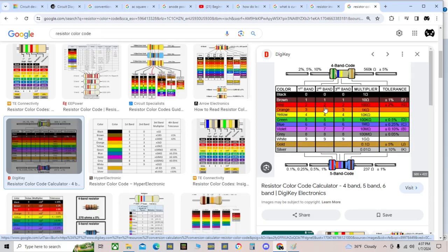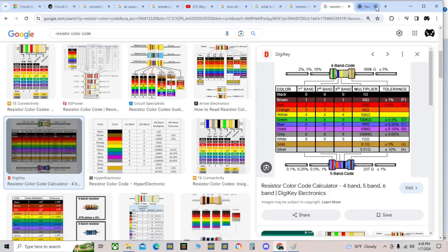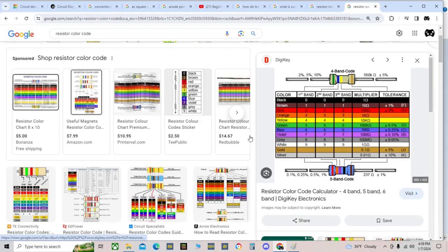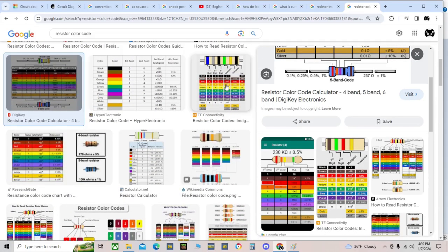Then we've got to find blue. 5, 6. Oh, multiplier 10. Oh, okay, I didn't see that. I'm blind. But yeah, just the multiplier, and then if they have more, you take whatever the last two are and subtract them from the total, so you get the regular digit number. You take these two, subtract them out, and it'd just be these three color bands. Get one of these on your binder. This is what you need on your binder.